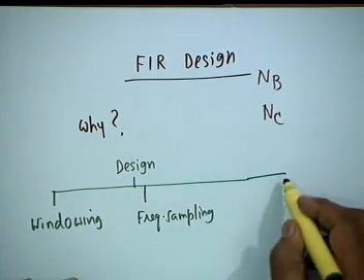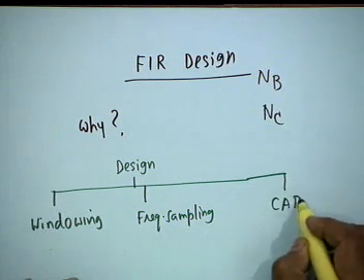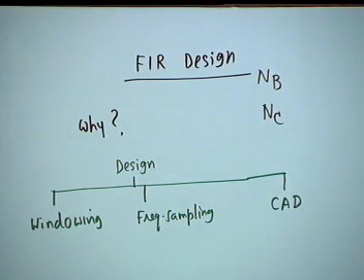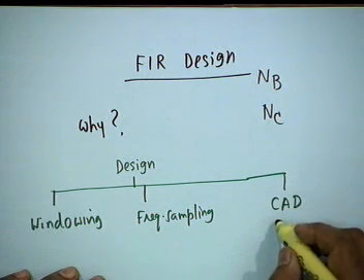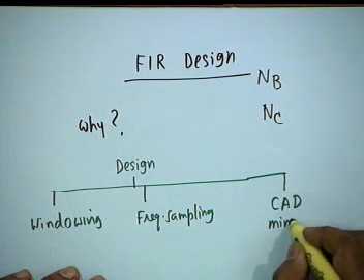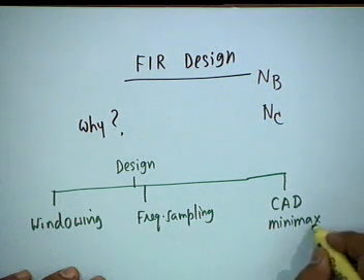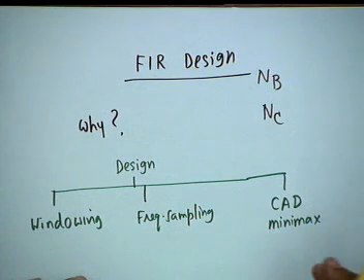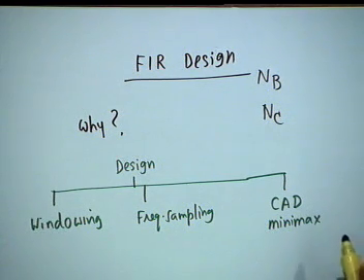These two are semi-analytical, and then of course you have the computer aided design of so-called optimal filters. They are also called minimax filters, minimax design, because in the computer aided design procedure using the Remez exchange algorithm, what you do is minimize the maximum error.